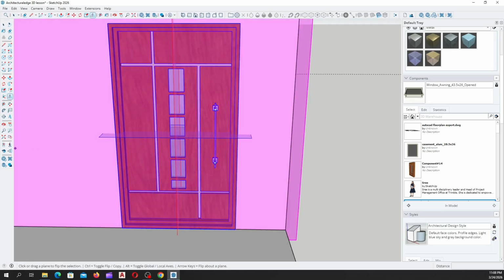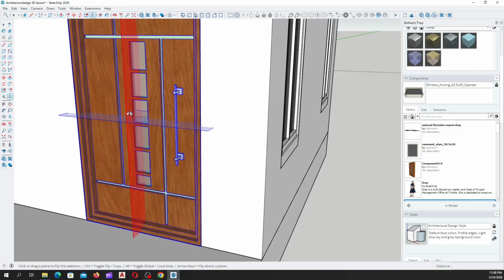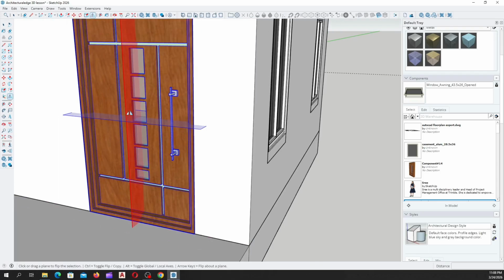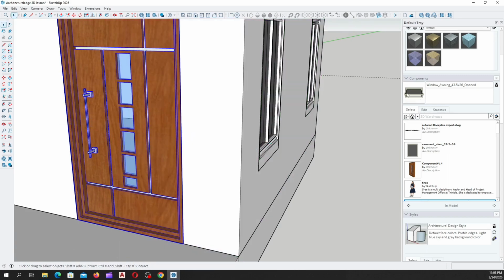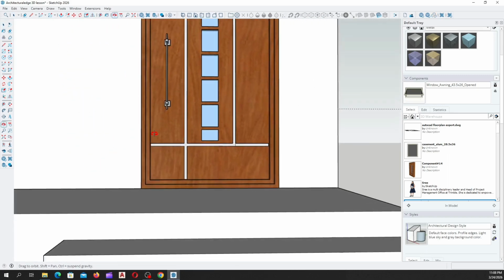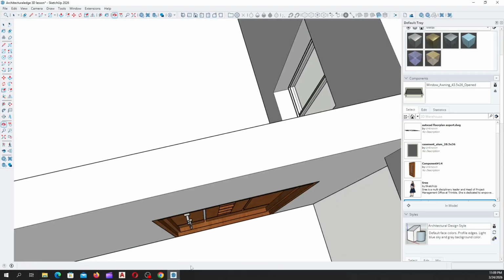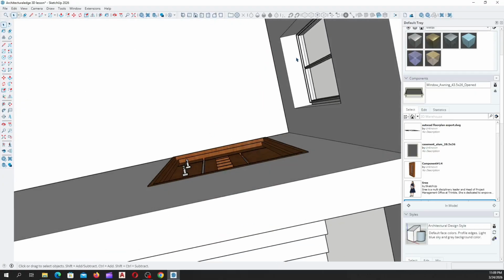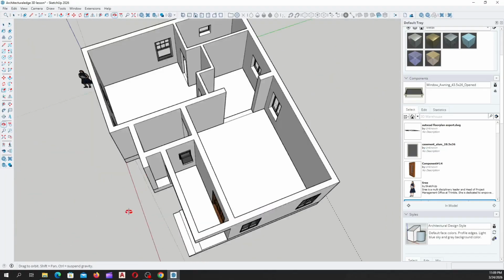All right, so you pick your flip tool, then you come to this point. Since we are flipping it on the red axis, you click on this point. So you see, automatically our door is being flipped to this other direction. So once you open the door, it's flush to this direction. All right, so what are we to do next?